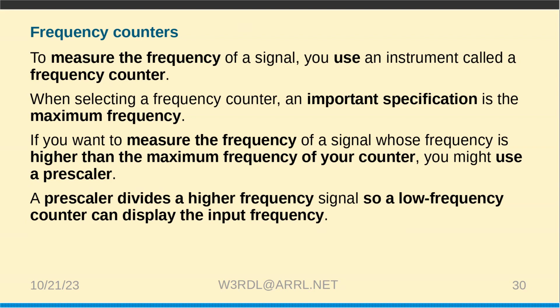That's very true. When I put on a longer length cable, the SWR goes down, totally different. It's perfect. I put 100, 200 feet on and got a really good SWR. You don't have a care in the world. Losses throughout the line heat up the transmission line. That's also the advantage of having an analyzer: you can go close to the antenna.